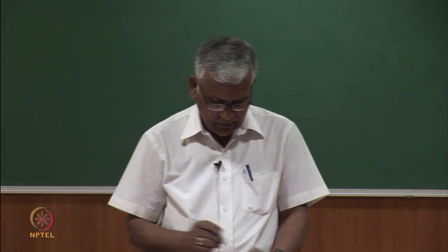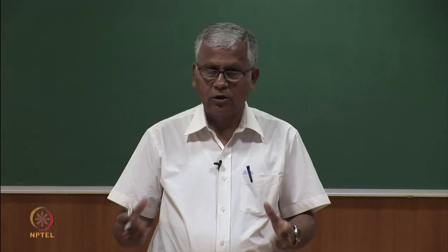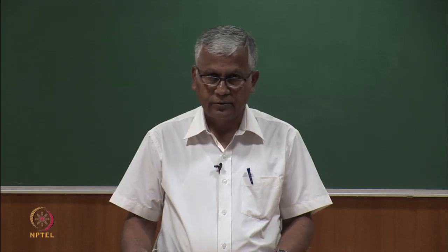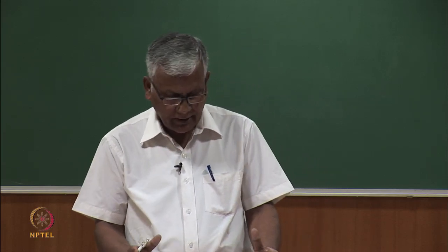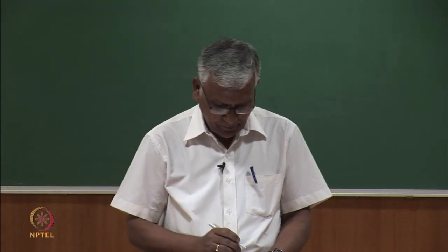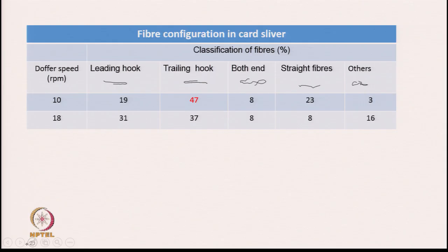So, once they are visible, it becomes easy for us to note down the configuration. We can trace the configuration on a piece of paper, or we can take photographs, and later on we can see the photographs and study the configuration. So, this is the technique known as tracer fiber technique. This technique has been used by many people to study the configuration of fibers.